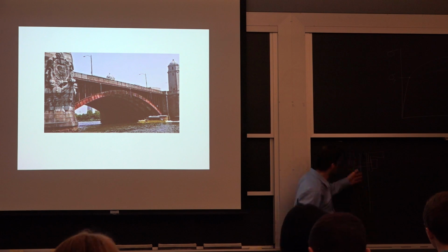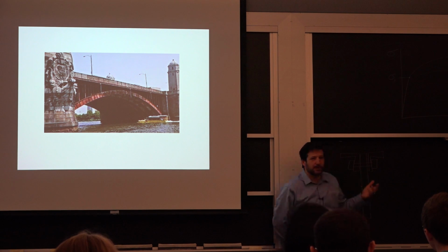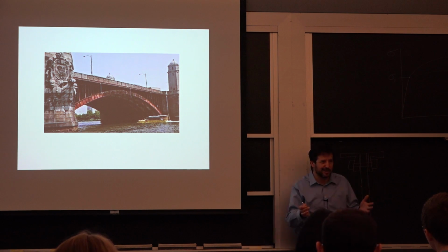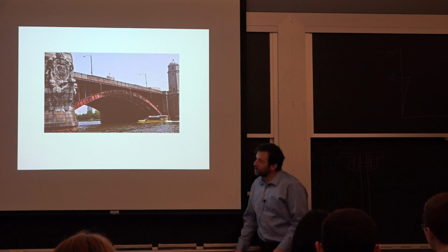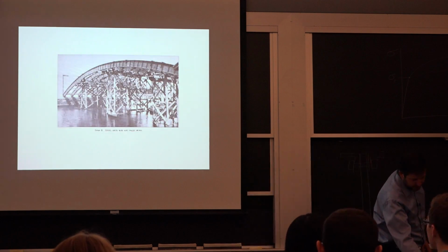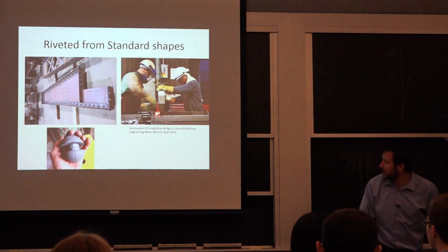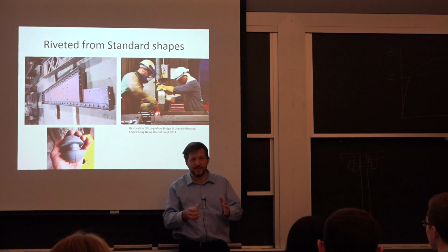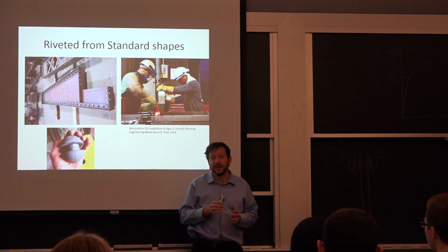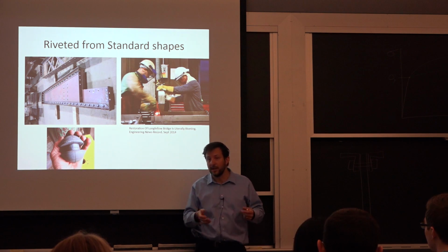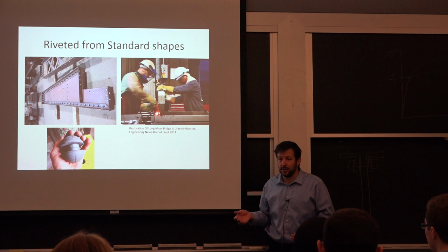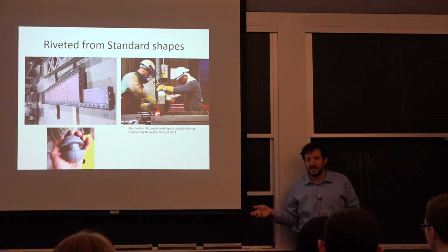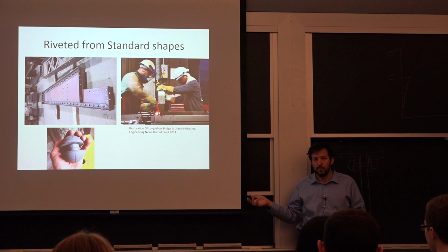If you do a riveted connection, the good news is, as long as you put the rivet in, it's great. If it's all put in and compressed, looking back to that image here, this is a solid piece of wrought steel that's in there. As long as it's there, it's not going anywhere. It's not like a weld that wasn't done the right way and could be very brittle, for example. So the chances of making a mistake in the process here would be picked up just by visual inspection.